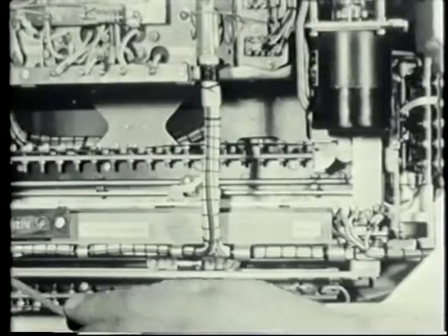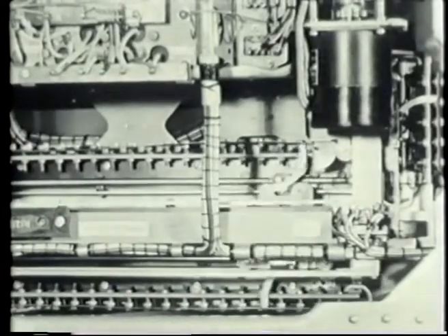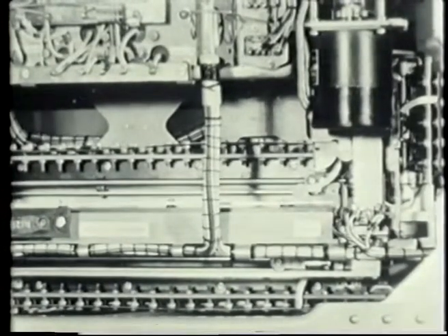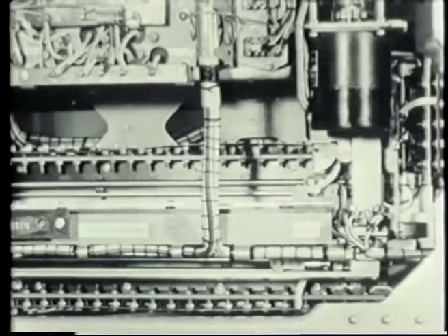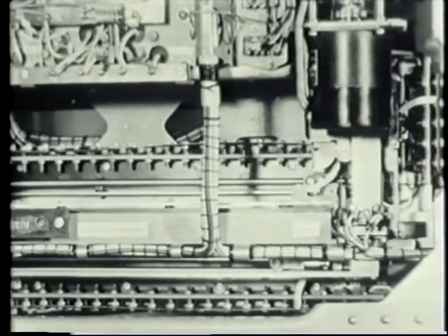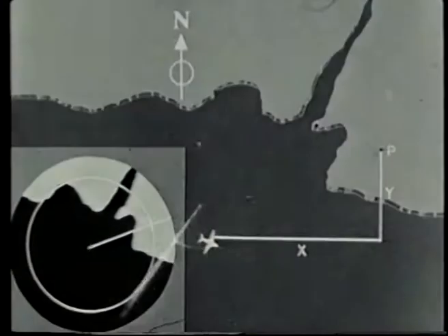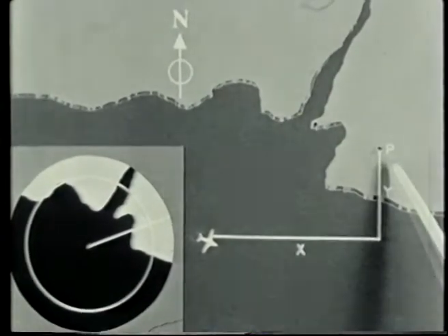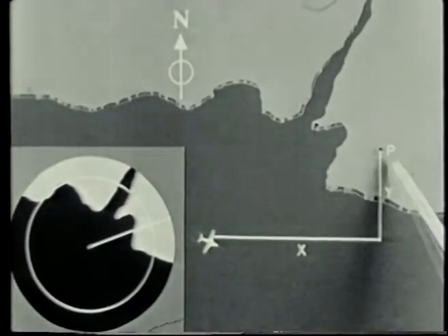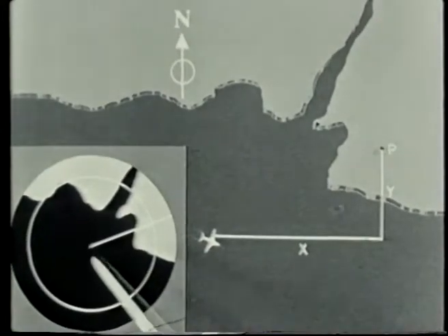The tape is made to move the track of a third potentiometer through a distance equal to the hypotenuse of the triangle. This potentiometer, therefore, delivers a voltage proportional to slant range, and this is fed to the waveform generator, where it controls the time delay of a range marker pulse, which brightens the PPI trace at the appropriate range. The point P on the ground, defined by the rectangular coordinates set up on the marker potentiometers, is now marked on the tube by the intersection of the range circle and bearing line.